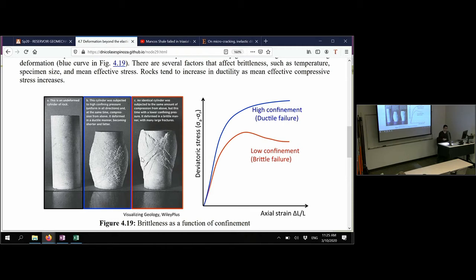And we didn't go to very high stress, but if you were to use a very high stress, your rock will start to fail quite differently, and the failure will be distributed all over the sample. And instead of having a very well-defined peak after which you lose all your stress, your rock will start failing more as a ductile material. And that's because now you have stresses acting in all directions, and your failure is not just a clear fracture, but it's distributed all around the rock.